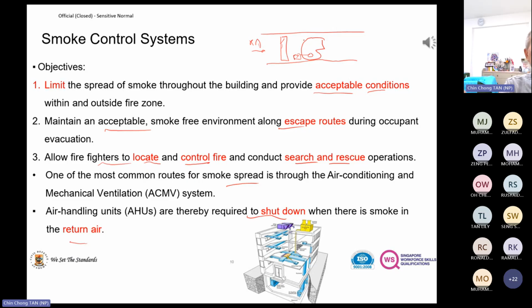What it's trying to say is that every fan, every air handling unit, we should have a smoke detector here. So when the air coming in carries smoke and hits the detector, it should stop the fan. However, when there's a fire, the main alarm panel should stop all the aircon systems altogether. This smoke detector here is also good for the motor. If the motor overloads and causes a fire, this smoke detector will be activated and it will stop the fan.